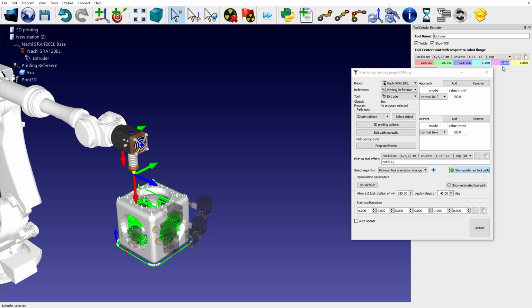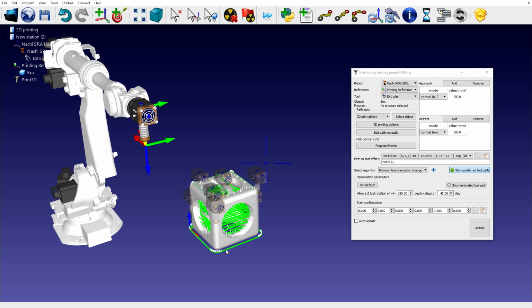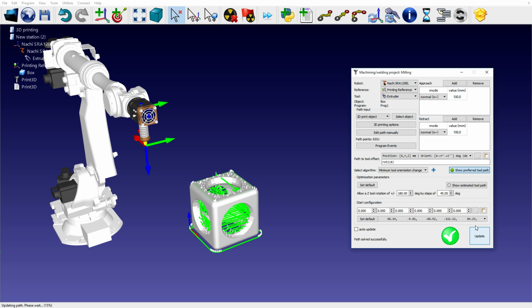We can double-click the tool and change the tool orientation manually. We can see that a rotation around the Y-axis of 90 degrees will place the Z-axis at the right spot. The Y-axis is the green axis, and the X-axis is the red axis. We could have also used the Alt and Shift keys to move the tool axes with the mouse.